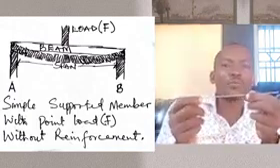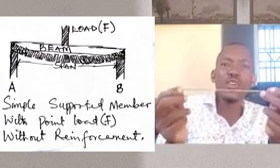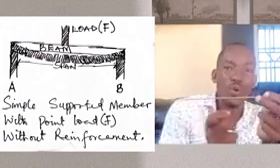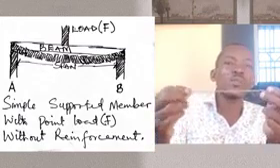But the idea I want you to get is, for a simple supported beam, where you need to put your rod is at the bottom, where you need to concentrate more is at the bottom and not the top. That's the idea I want you to get. And I'm not by any means teaching you so that you go and do it yourself without an engineer. It's always advisable for you to use a competent engineer to do your site activities.